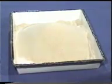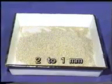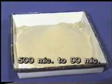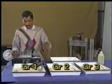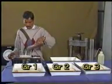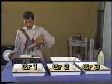The particle size of grade 1 sand varies from 2 to 1 millimeter. Grade 2 sand varies from 1 millimeter to 500 microns, and grade 3 sand varies from 500 microns to 90 microns. Let us now start with the testing of compressive strength of cement.